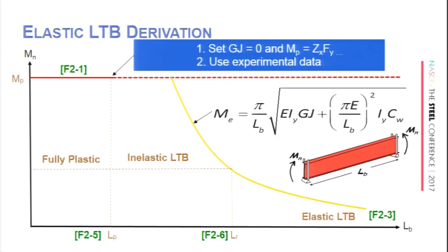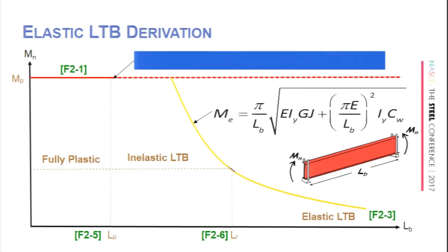And you can all take a big breath that we're not going to go through all the equations that led us to that conclusion, right? So the ultimate conclusion is that the line that we draw between these 2 points to define the inelastic lateral torsional buckling region, sure, it's anchored in the appropriate equations down here, and then it's really experimentally derived on up to this point here. Now, it is backed up with equations, and we're not violating physics or anything like that. But really, that's how we come up with this. In class, I love to get up there and just do a bunch of dots. Here are all our tests. We draw a line through them, and that's where we come up with this region. Okay, so more empirical than theoretical. But that defines our region.